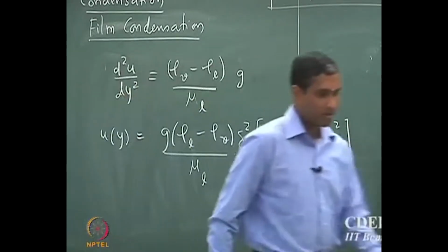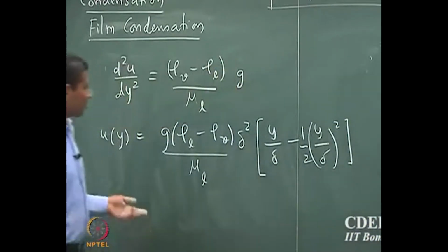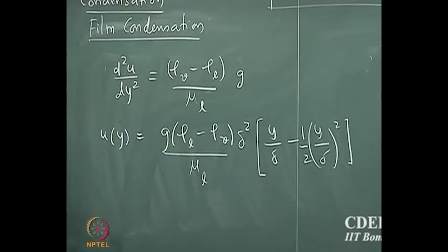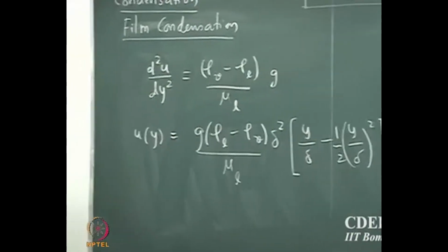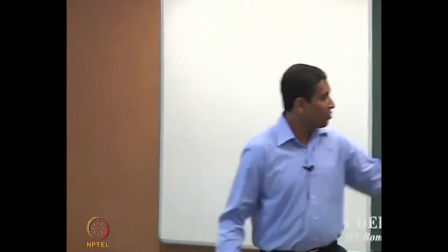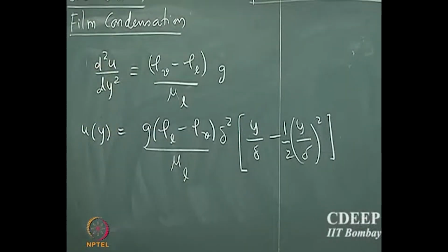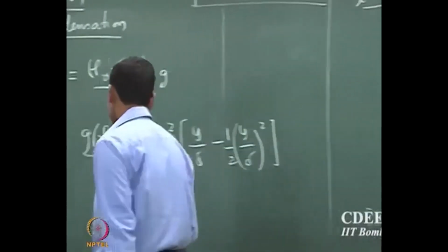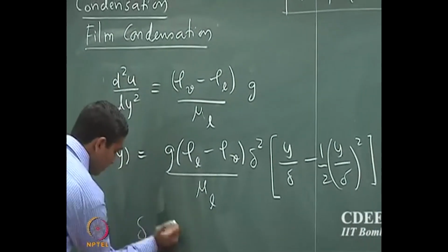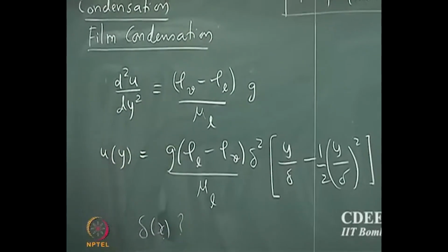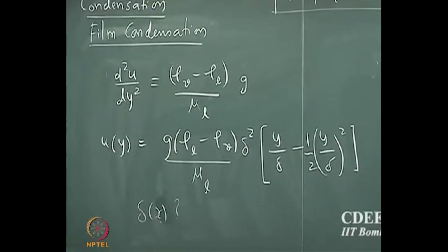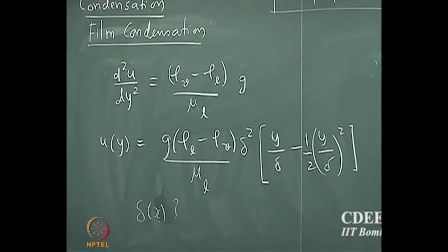Alright. So now, do we know the velocity profile from this expression? Yes or no? We do not know what delta is. We still do not know the velocity profile. So really the exercise here is to find out the boundary layer thickness, delta, at any location. Until we find the boundary layer thickness, the problem is not complete. We cannot find the velocity profile, and in fact the same issue will continue when you write a temperature balance. So how do we find this?